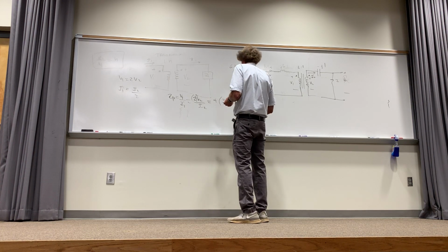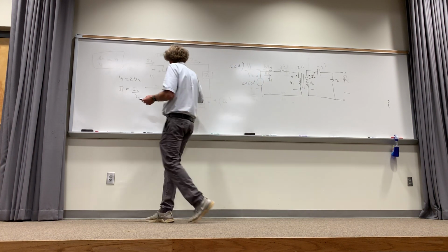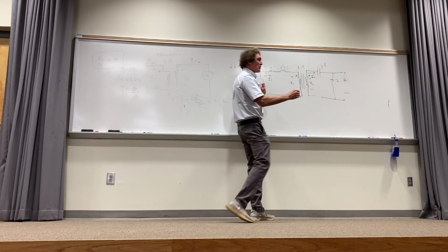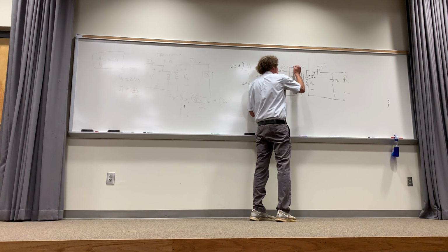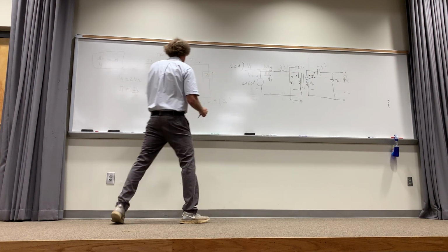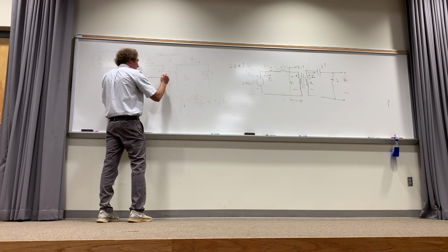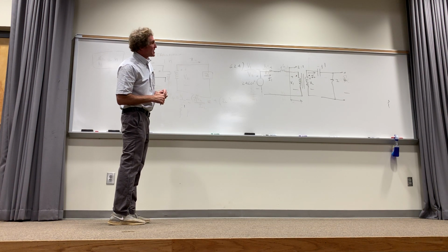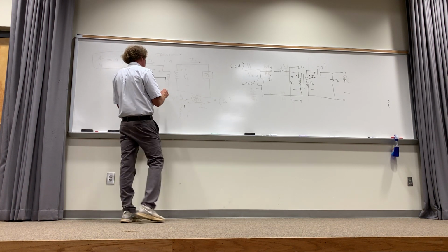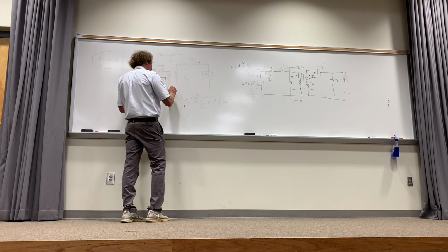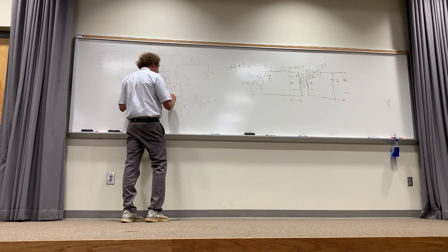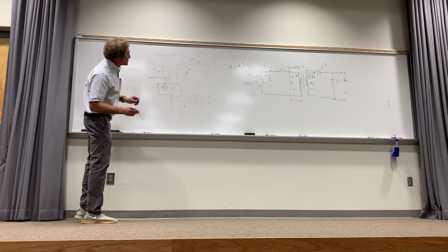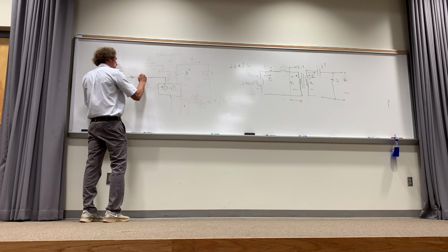Now when you take a look at that, and I draw this back on the primary side, I can replace this entire coil and everything over there with one single thing, and that's the reflected impedance. The reflected impedance, in this case, is going to be equal to 4 times 2 minus j1, just so everybody sees where it comes from, and that is simply the 2 squared. Now I put back the 4 plus j6 that was there in the first place.